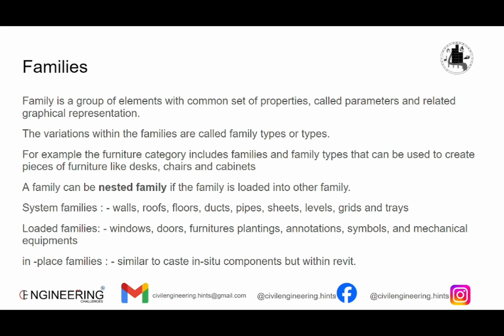Loaded families are the common type of families that are created by an architect in order to finish the model. These families are windows, doors, furniture, plantings, annotations, symbols, mechanical equipment, and so on. There are many families in the case of loaded families.